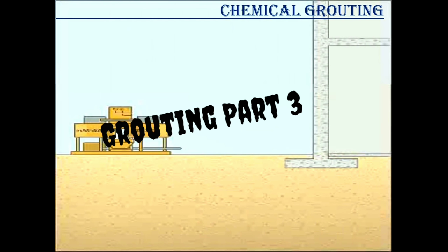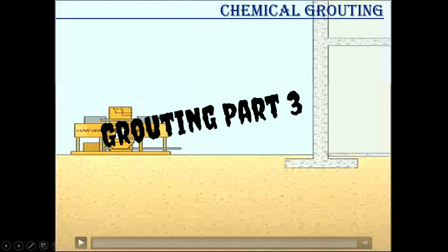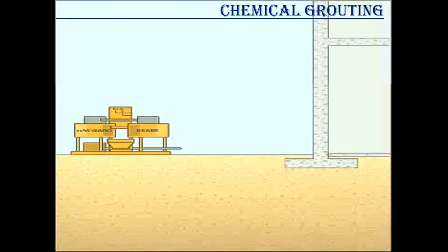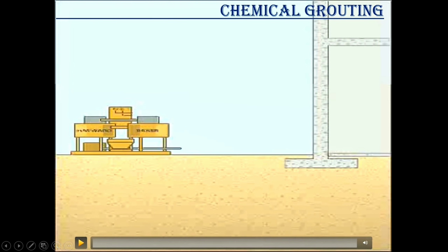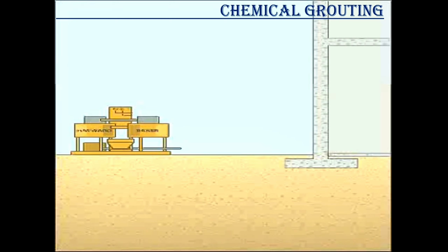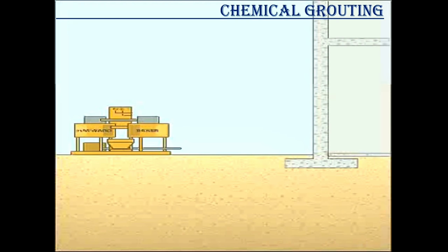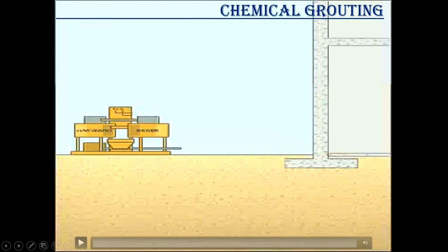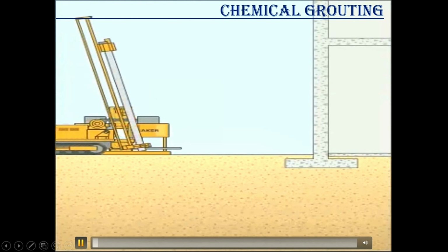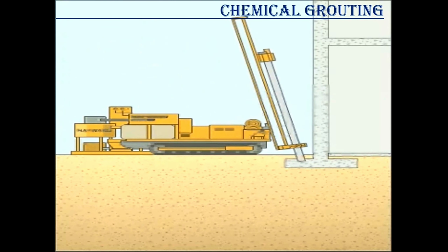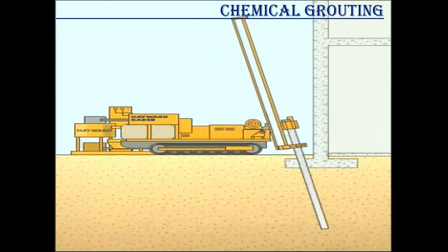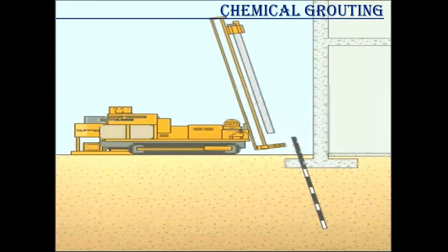Now the next one is chemical grouting. As the cement grouting indicates, the same applies to chemical grouting. The answer is: when you have a water table problem nearer to your existing building and you need to change the physical characteristics of any water-contaminated area, at that time I choose chemical grouting. In chemical grouting, we introduce the grouting process nearer to my foundation work.